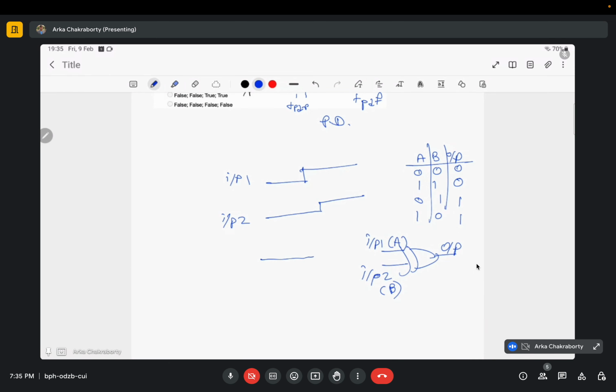Now what happens? Generally, sometimes there are internal delays between signals due to difference in the path taken by the signals to reach a particular stage of the circuit. This leads to a small amount of skewness, or a small amount of shift between them. For that reason, between these 2 points, instead of getting a 0 output like this, I will be getting something of this order. This is my output. This is the glitch that we are getting, and this kind of glitches are common in circuits. So as at this position my output is not what is expected and it is contaminated, it is called the contamination delay, the delay between this and this, or this and this.